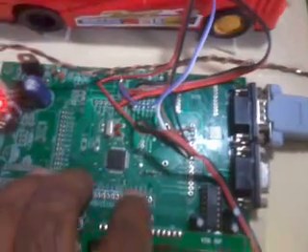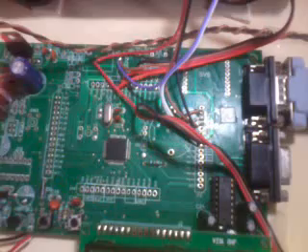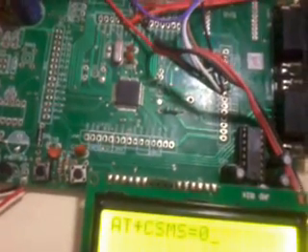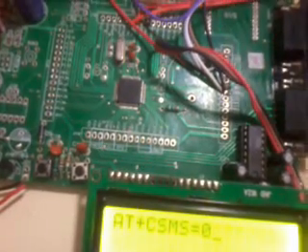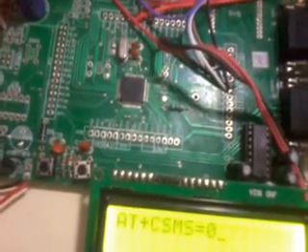Here this is an LPC 2148 development board. In this board we have 2 UARTs, and sensor interfacings are available. The LPC 2148 is a 64 pin IC with 2 ports, port 0 and port 1. Port 0 consists of 32 pins and port 1 consists of 16 pins, a total of 48 bidirectional input output pins. The remaining pins are crystal, VCC, ground and battery.